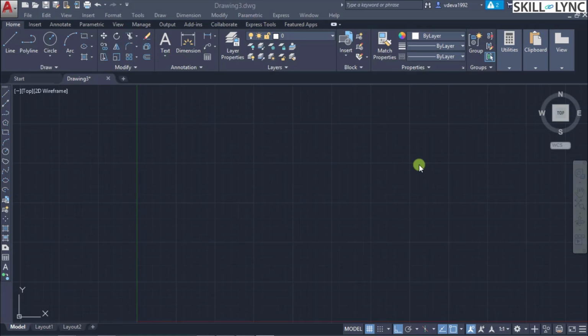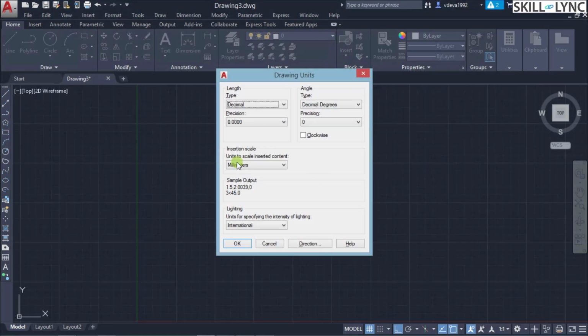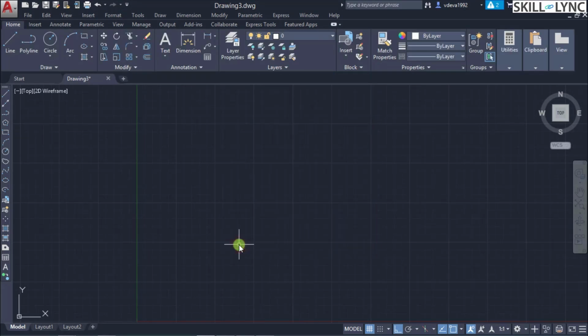So in the new drawing we'll start off with ensuring the units are in millimeters, and next the limits have been turned on, and also the lower and upper limits for A3 or the A2 size or whatever you are working on has been ensured. So we are using the same limits session. To ensure that we stay within the extents, we first click on the zoom extents option so that the maximum dimension of the limits is captured.